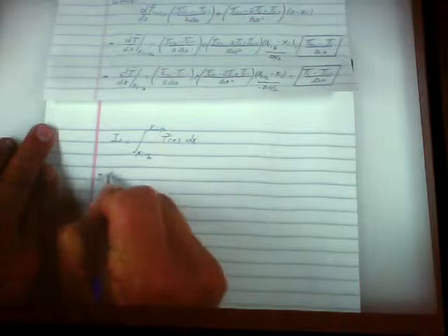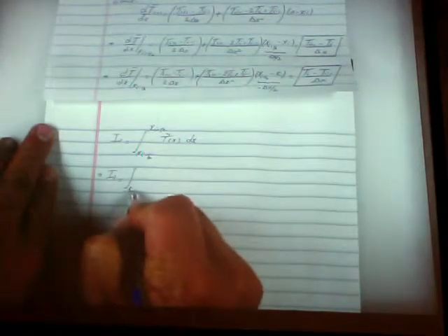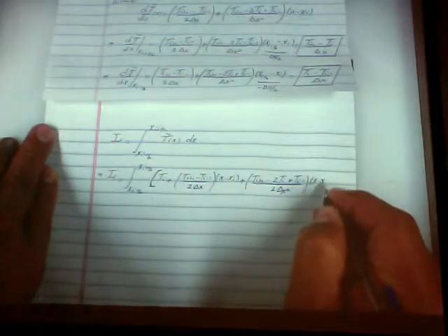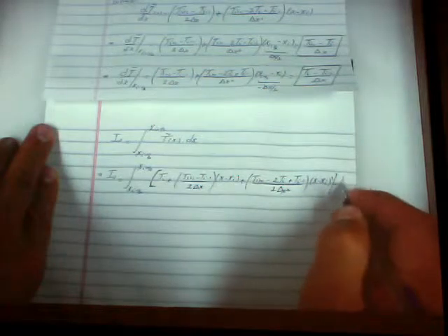So therefore, I1 is the integral between x_{i-1/2} and x_{i+1/2} of, maybe we should do brackets, T_i plus (T_{i+1} - T_{i-1}) over 2 delta x times (x - x_i) plus (T_{i+1} - 2T_i + T_{i-1}) over 2 delta x squared times (x - x_i) squared, dx.